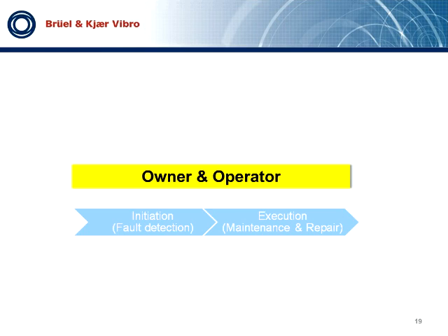Now, there is one possible downside to this model, and that is when you do in-house CMS, if you have a large fleet of turbines, that CMS is a full-time job. Very often the CMS analyst or the responsible will have other responsibilities, and then sadly won't have time to look at all these alarms. So again, what's lead time? If you don't have time to look at it, you don't have any lead time. So it starts really there. You need to have a dedicated CMS team, or at least CMS specialists that are taking care of this 24/7, because this is a full-time job.